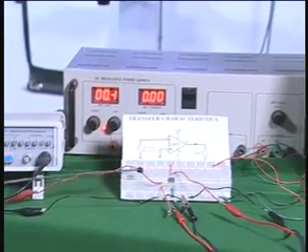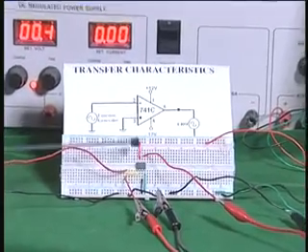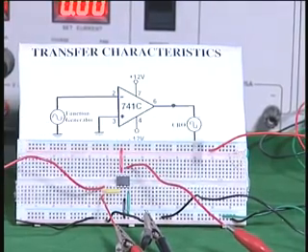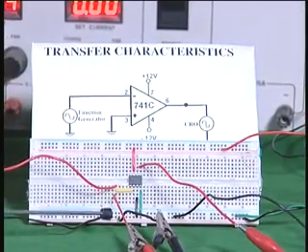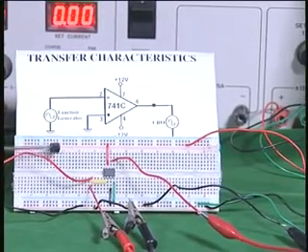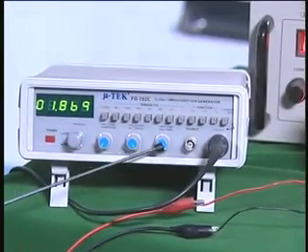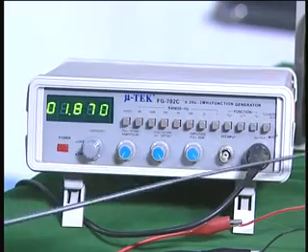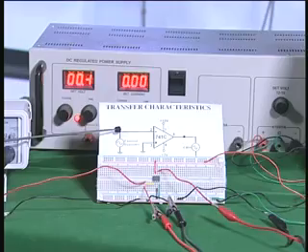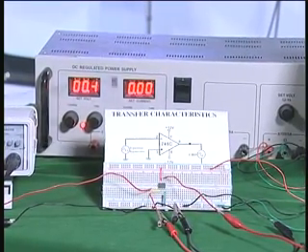The pin number 2 is connected to the oscillator, pin number 3 is connected to ground as shown in the picture above, and the output pin number 6 is connected to the oscilloscope y input, and one other extra terminal taken from pin number 2 is given to the x input of the oscilloscope. Now I have a large amplitude, nearly about 1 volt or so using this knob, and therefore with reference to terminal 3, the terminal 2 voltage will go plus 1 volt to minus 1 volt or whatever, and therefore it will keep going up and down.